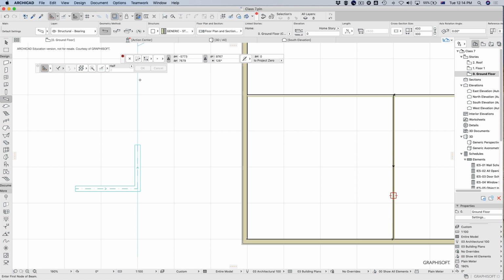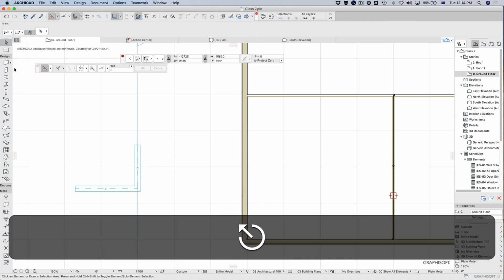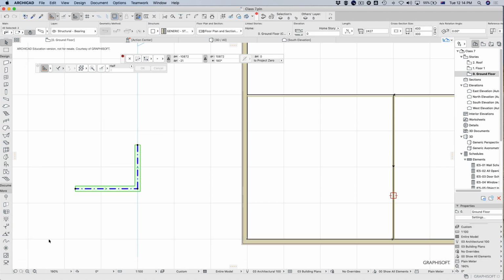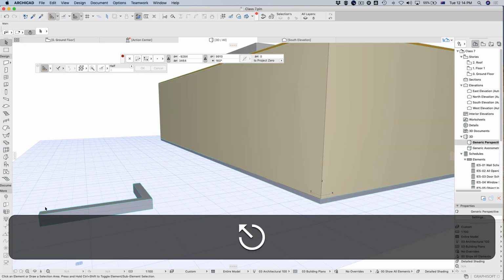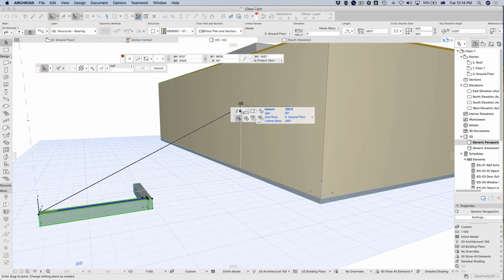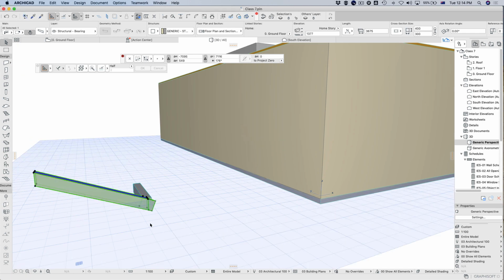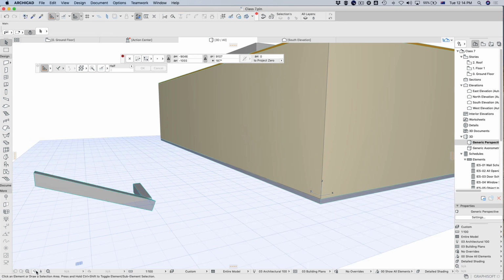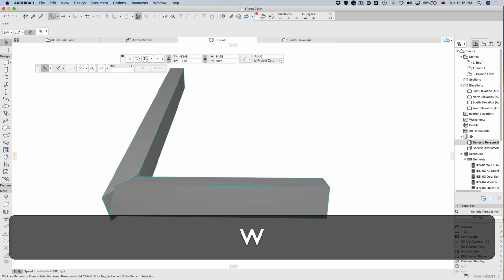Very similar to walls, except beams can go on angles as well. Okay. So I can actually grab this point, and let's just do this in 3D. I'm going to grab these and go to the 3D view. So I can actually grab this little reference line, and you'll notice that I can lift it up. Now, of course, this is going to cause all sorts of problems here because it's just impossible for those to join.